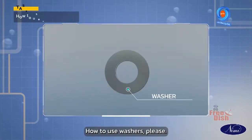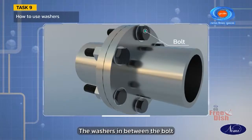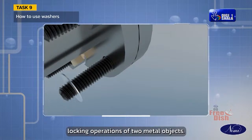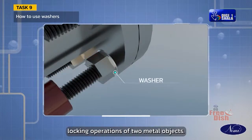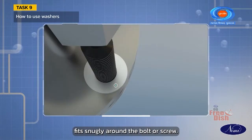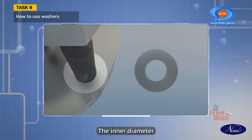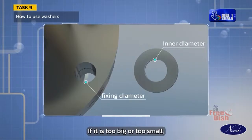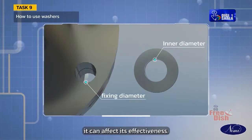How to use washers. Place the washers in between the bolt and nut for tightening the flanges. Place the washers for various locking operations of two metal objects. Ensure that the washer fits snugly around the bolt or screw. The inner diameter should be slightly larger than the fixing diameter. If it is too big or too small, it can affect its effectiveness.